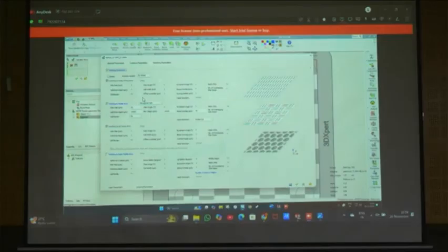Okay, you can see here, this is like a hexagonal, you can see the thumbnail here, rectangular, and if you want the alternative, that is chessboard actually. Vertical, horizontal, strips are there. How many scanning strategies are there? Strips we can do, rectangular we can do, rectangular alternative means chessboard we can do, island scan strategy we can do, hexagonal we can do. Again strips, horizontal and vertical both, double centering we can do.